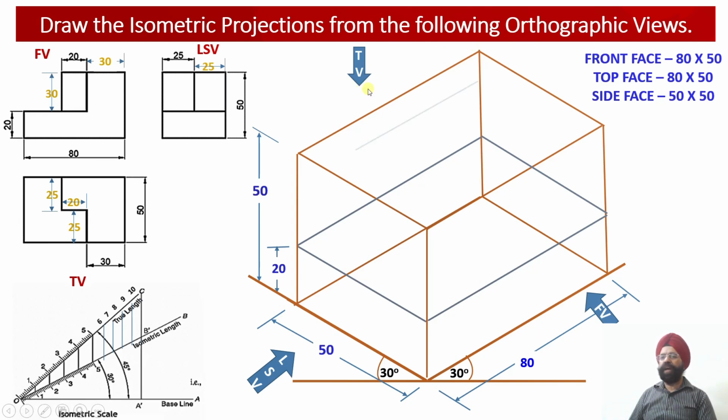So let us start working upon the element number 2. So please see, I have marked this particular edge equal to 50 millimeter. So this is the point, right? So how have I obtained this? Either you can leave 30 from this side as we have discussed, or you can mark 50 millimeter from this corner over here. So any dimensions which I am showing on the isometric projection marked with this lighter color are only required for the purpose of guidance.